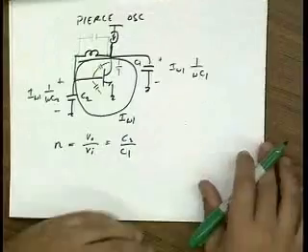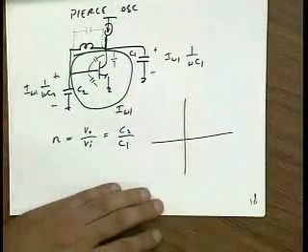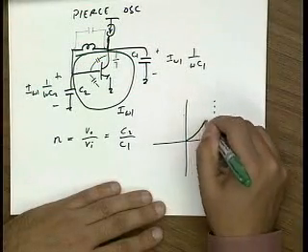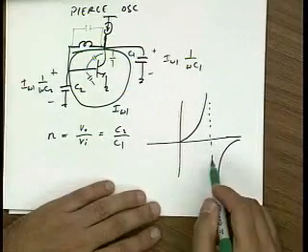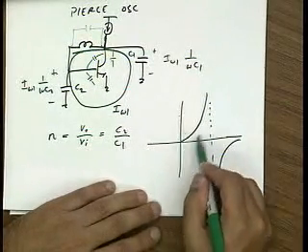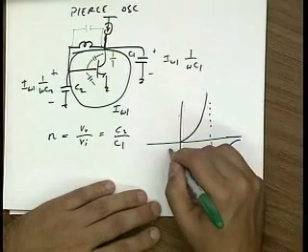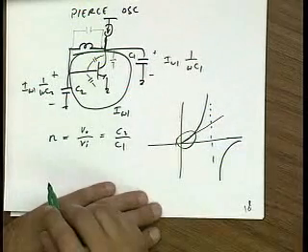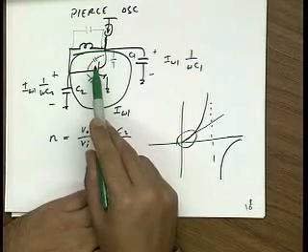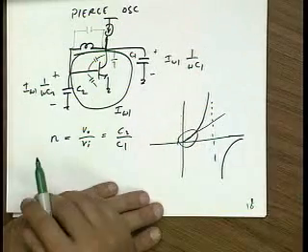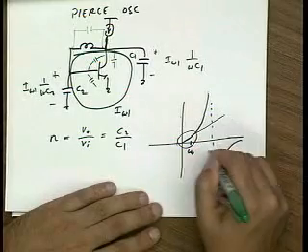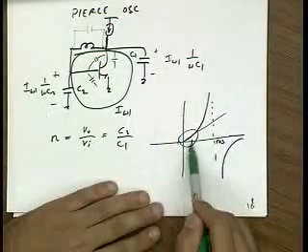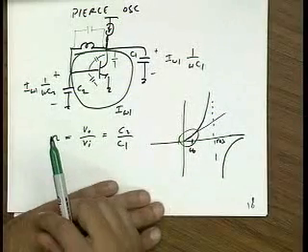Well, so if I have an LC tank and I look at the perfect LC tank, this is what the reactance looks like, right? So this is resonance. So as long as I'm below resonance, the thing looks inductive, right? If I'm really below resonance, then this looks like a straight line. It looks almost like a perfect inductor. So as long as C mu is much smaller, right, so the resonant frequency is much higher than the frequency I'm operating at. So let's say this is omega naught, and this is the resonance of C mu plus L. If I'm operating over here, the effects of C mu are pretty negligible.